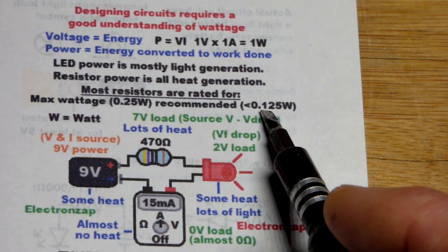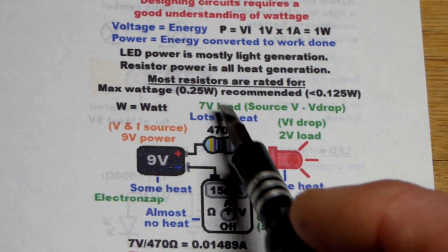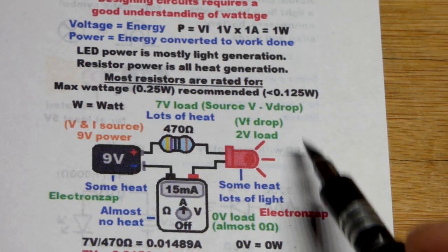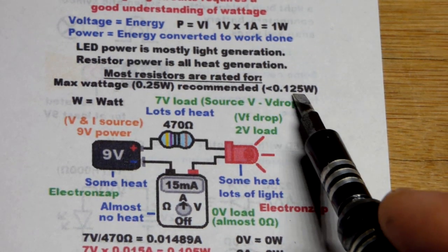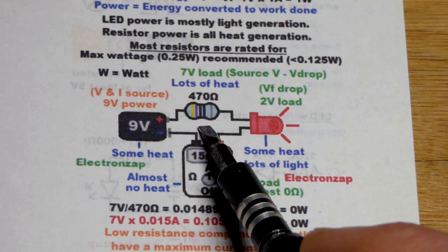The resistor will probably last forever, but if you get it close to its maximum wattage, good chance it will burn out. And so just be aware of that. And you don't have to worry about it getting too cold. That's no problem. Just try to stay below half if you can. So that comes with resistors that look like this.